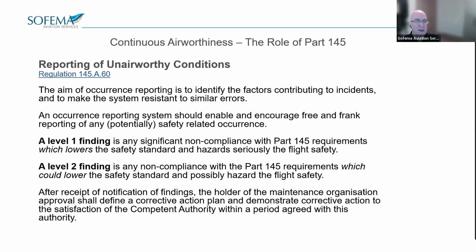It's also possible that some inspections that are carried out in between the major checks will detect a non-compliance, the condition of the aircraft not being acceptable, or maybe a task was not carried out. However, the intent is not to require the maintenance organisation to find or become responsible for any hidden non-compliances which are not expected to be discovered during the scheduled maintenance programs. So, as I said, the non-compliances of this sort are expected to be detected either during the course of later inspections or during scheduled audits.